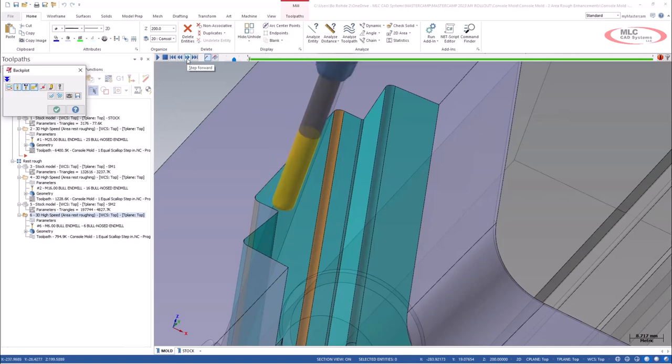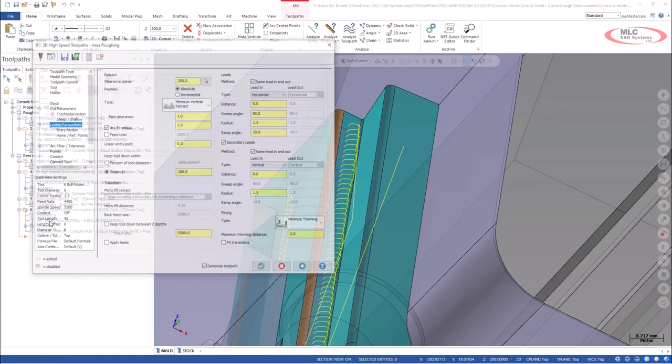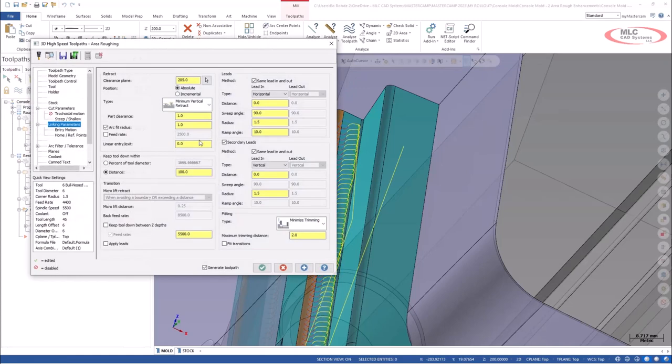You see it arc down, it's going to arc up and just loop around to the next toolpath as it works its way down. But we might be able to clean that up a little bit. So I'm going to jump into my parameters and go to my linking parameters, where it controls my lead in and lead out. And instead of a 90-degree sweep, I'm going to change this to a 120-degree sweep.